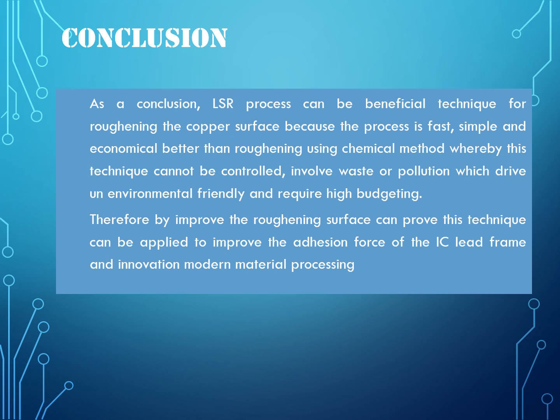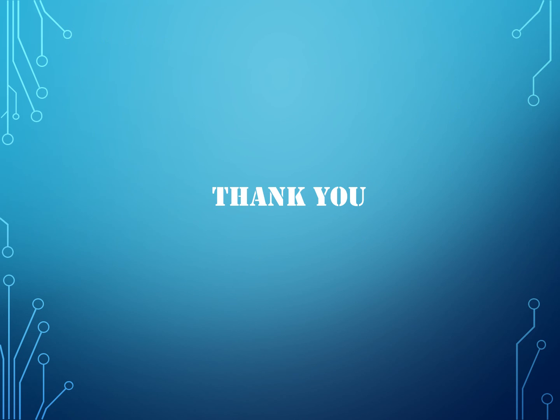As a conclusion, the LSR process can be a beneficial technique for roughening the copper surface because the process is fast, simple, and economical, better than the usual chemical roughening method, whereby this technique cannot be controlled, involves waste or pollution which is not environmentally friendly, and requires high budgeting. Therefore, by improving the roughening of the surface, it can prove this technique can be applied to improve the adhesion force of the IC lead frame and innovate modern material processing. That's all.